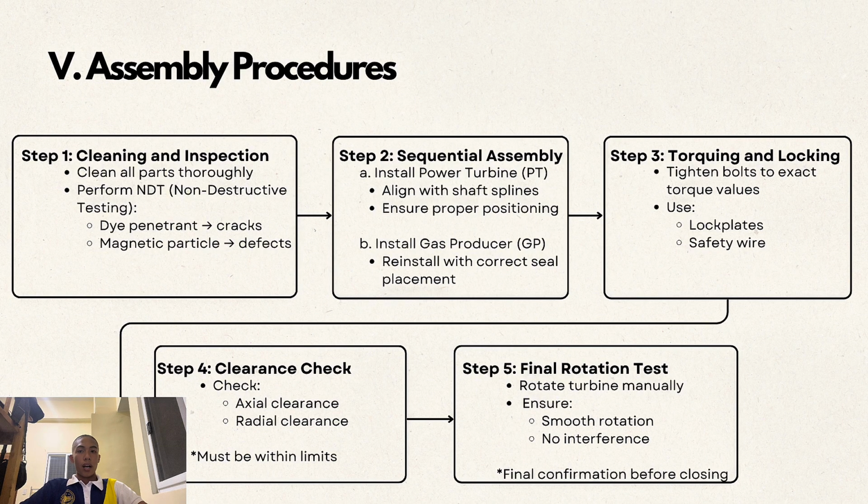Now we move to the hot and rotating components. First, slide the first stage turbine wheel onto the main shaft, followed by the spacer. And second, install the second stage turbine wheel. Note the curved couplings. This must be perfectly aligned to ensure balanced rotation.